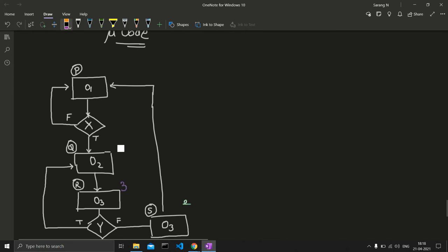Now let's start over. You have to do this every time you are building a microcode for an ASM in the counter-based approach. Let's say p here is 1. If p is 1, the false is automatically a jump, so the true one should be sequential. We have 2 here. After 2, we prefer a jump address, so it will be 0, right? So 0 to 2.